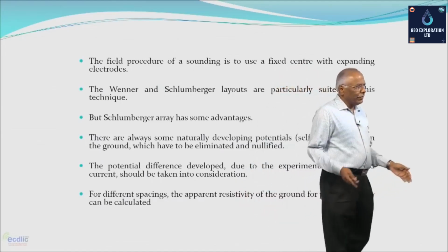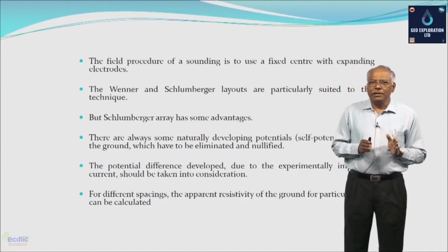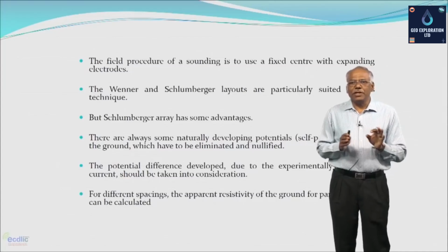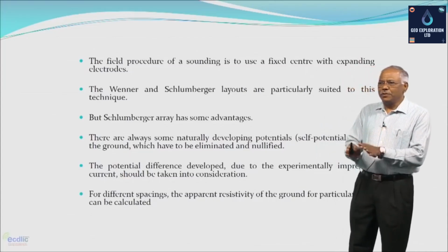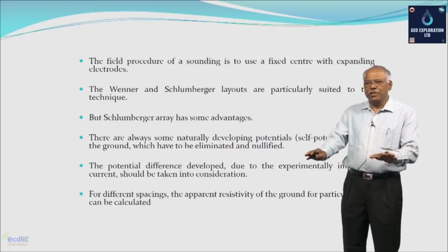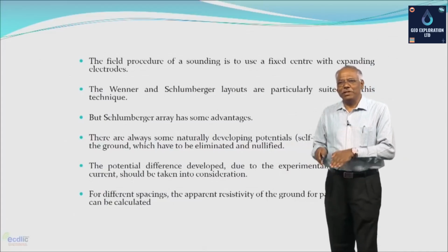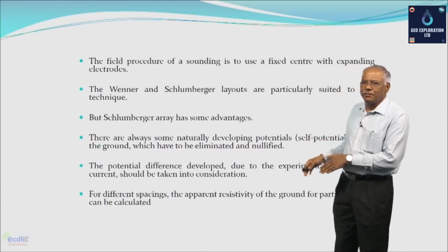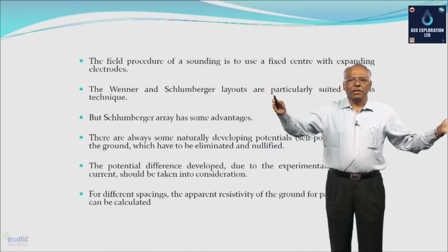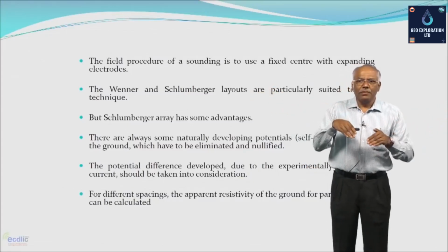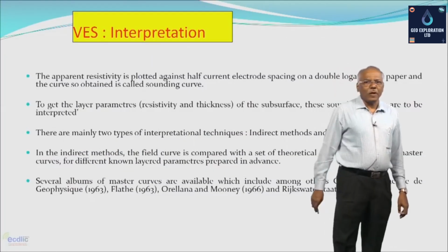In the field, when you are actually applying the vertical electrical sounding, the procedure for this is very simple. As I said, you identify the resistivity low, then put your instrument there, and from 1 meter down to the depth of 50 meters, 60 meters, 70 or 100 meters depth, you keep on increasing the distance between the current electrodes, so that you can go to deeper and deeper levels, and that is what is actually done here.